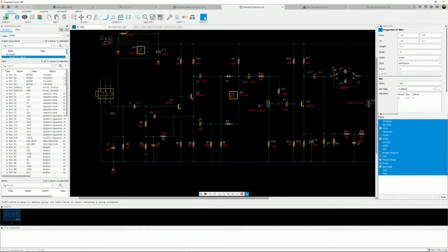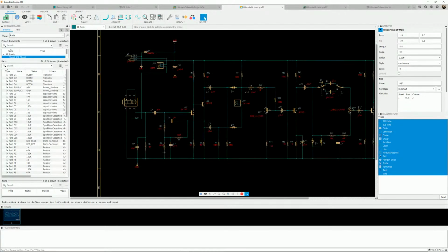Other circuits used a transformer, and they would drive the audio signal through a little transformer, and the secondary was center tapped with 2 diodes. Just the phase splitting. Yeah. This one just uses a transistor to do it.